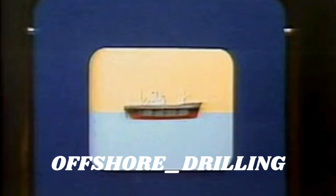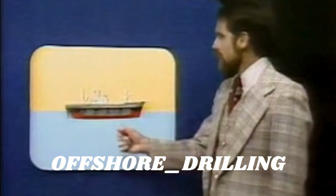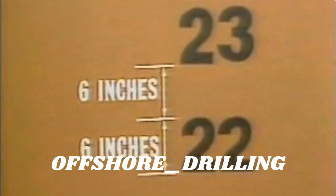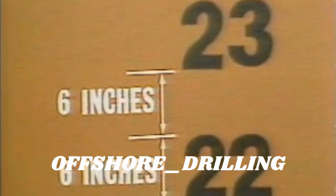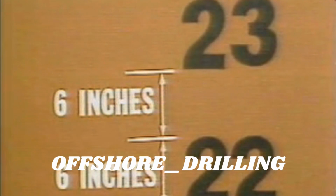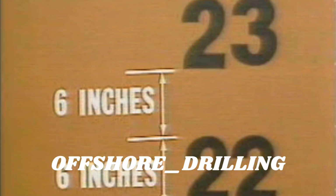The draft of a vessel is the distance that it is submerged in the water, or the depth from the bottom of the keel to the water line. Draft marks are painted on both sides of a vessel, at the bow and also at the stern, in the following manner. The numbers are 6 inches high, with 6 inches space between them. The bottom of each number rests on an even foot of draft. This system of marking enables us to eyeball a vessel's draft with a high degree of accuracy.